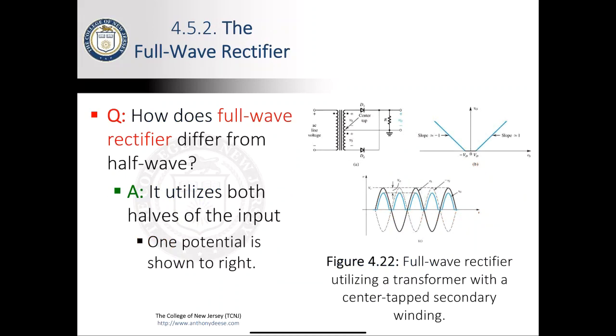Okay, so now let's jump into the next topic. Well, it's related to the first one, the full-wave rectifier. Now, a full-wave rectifier differs from the half-wave because instead of taking this right here and spitting out this, it will give us both sides of the waveform. This is advantageous for several reasons. One main reason is that you have more power output.